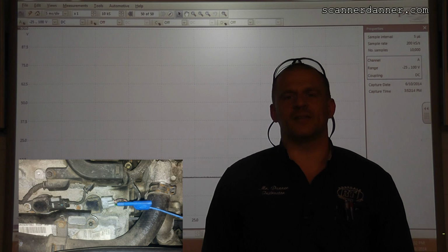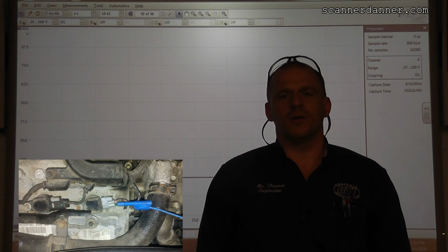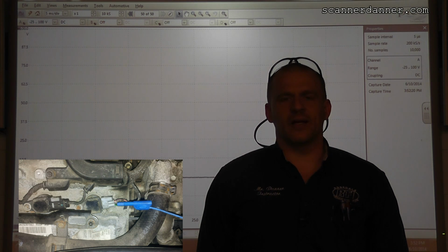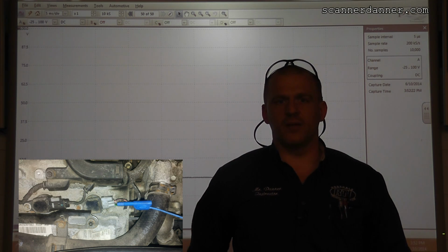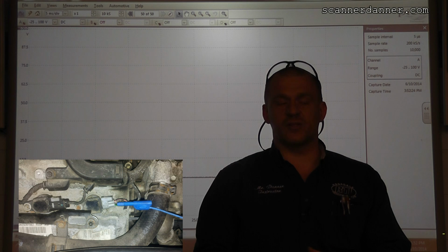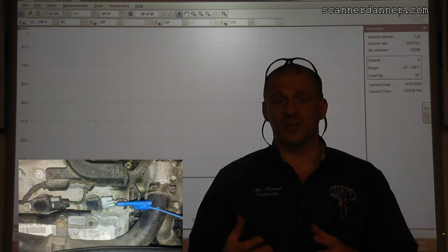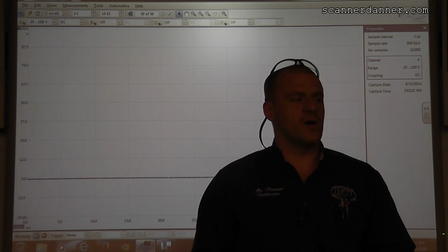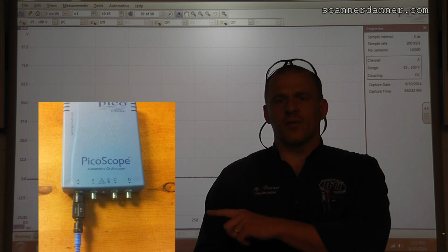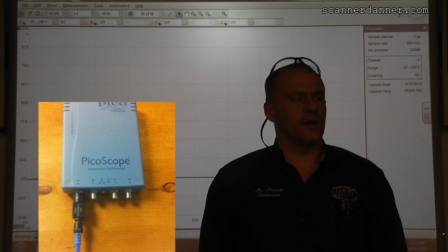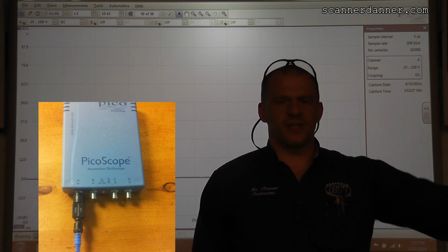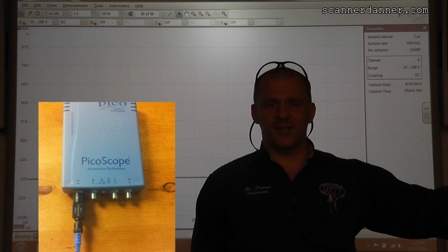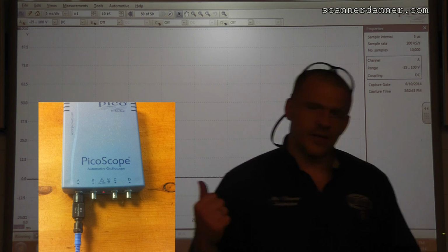What you're looking at is the blue channel. Channel A is connected to an ignition coil, and it is a coil-over-plug design. The transistor is not inside the coil. We're actually looking at coil primary here, and I'll show you a picture now. The scope, you can see, take a look right here. The attenuator is set up because this thing spikes over 100 volts and I want to protect my scope. So that's the setup. I'm going to start the car, let you see the waveform.